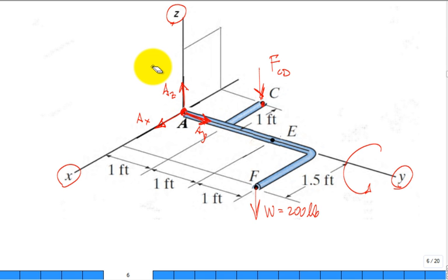What did we cut out? We cut out that journal bearing. What does that journal bearing exert on my rod, my body? It could exert a non-zero E in the X and a non-zero E in the Z. It could also exert a non-zero moment at E about the X-axis. But if it's aligned perfectly, like we want our bearings to be aligned, then that will be zero.